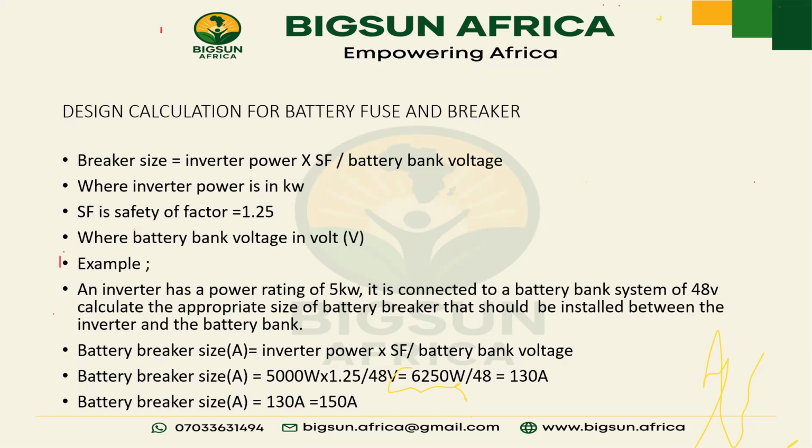So now we are looking at design calculation for battery fuse and breaker. The breaker is going to be between your inverter and the battery. I know most people don't use battery breakers, but it's very, very important, so always try to add it to your quotation.